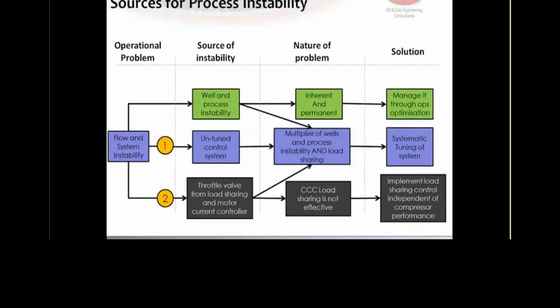The second thing that obviously we found out was that the anti-surge control system was not tuned properly to the demand of the process itself. And frankly, because there are 3 different stages of the compressor and 2 different trains of compression, and the overall interaction between the trains, it makes it really difficult to try to go offshore and try to play around with the control system, try to tune it.